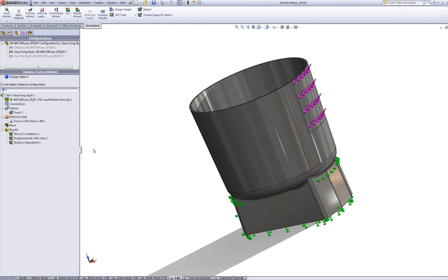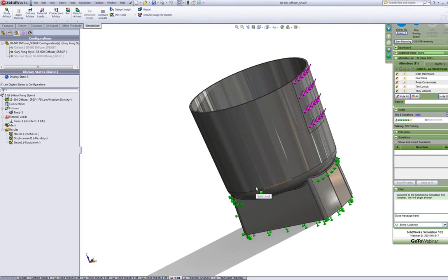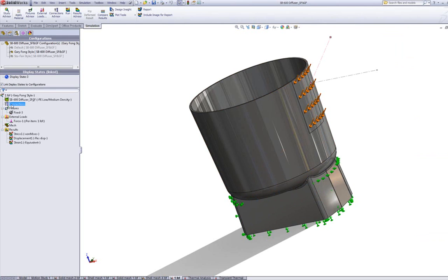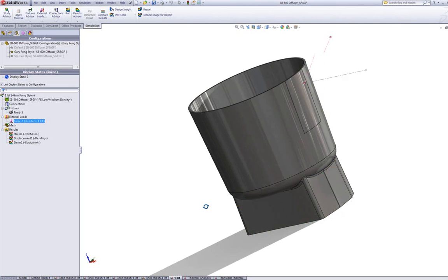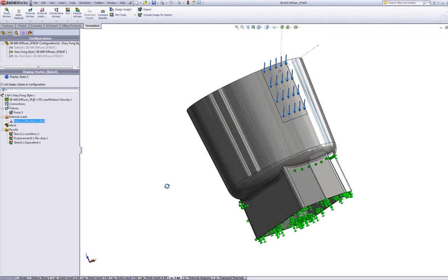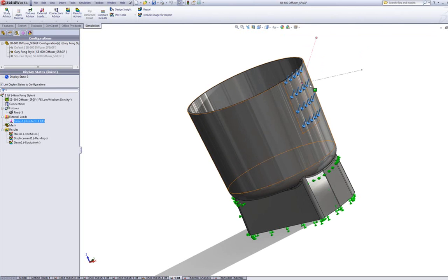To give you an idea of the scenario we were simulating, this flash diffuser was on top of this flash, and someone knocked it over with their hand or their elbow. Maybe this photographer was shooting at some event, and some bystanders smacked it and deformed the diffuser. So we were doing that. We were simulating this by applying a fixed geometry condition onto the base of the diffuser, and we were simulating the load at a particular angle, a simple 1 pound force load on that face that we have here.